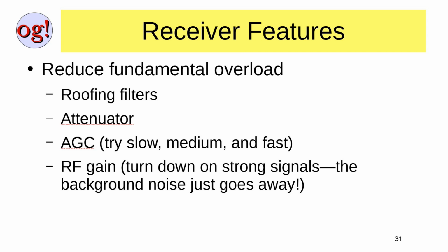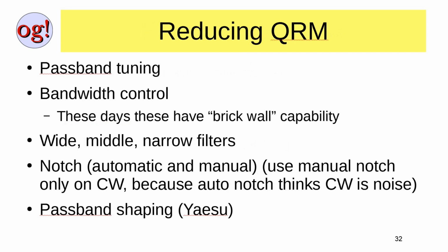Another thing you can do, and a too much unused technique, when you're talking to somebody with a strong signal, turn down not the audio frequency gain, but the radio frequency gain. If you'll turn down that on strong signals, the background noise melts away. It's like magic. Of course, radio's like magic.